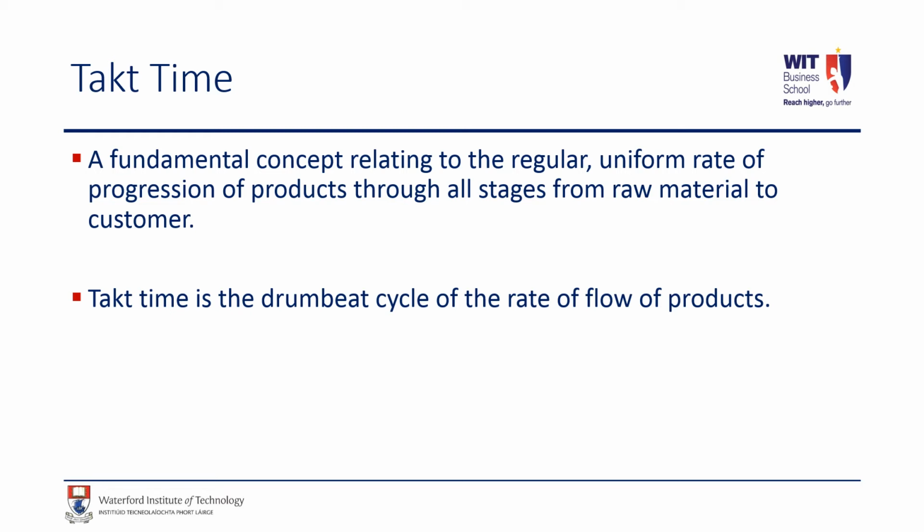So if we've got a process or a value stream that's manufacturing products or providing services to meet customer demand, the takt time is how much time you have to produce 1 unit of product. So it's the rate at which you produce 1 unit of product that will enable you to meet your average demand for a particular period of time, be it an hour or a day.